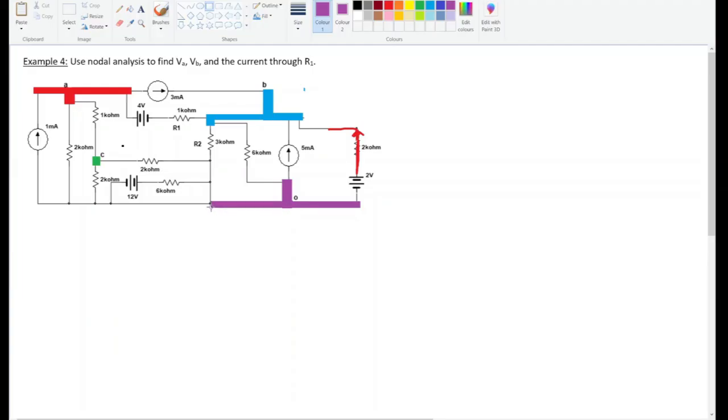First we're going to extend this node. This will go up as well, up to here, and then up to here, and keep on going to here, and here, and here. It's a gigantic node, and we're going to call it the ground node for two reasons. The first reason is that usually on these electrical schematics, the bottom row is the ground node. The second is that we can actually define the ground node to be wherever we want it to be.